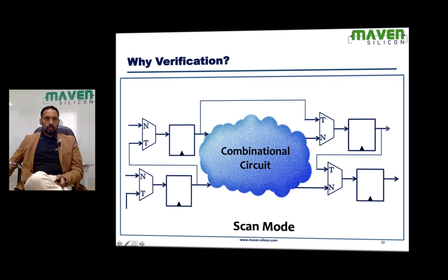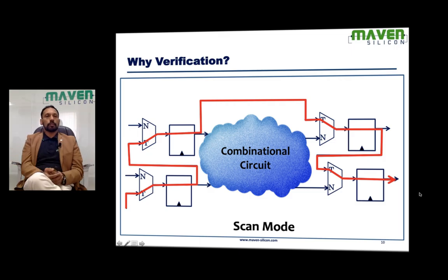But during test mode, it connects all the flip-flops like a scan chain, something like a shift register. So we would be able to pump in a stream of bits through all the flip-flops.